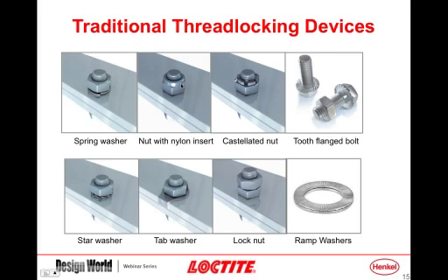The nylon insert takes a different approach. Here they're actually using a material to fill in the empty space on the threads. And it's an interesting approach, but it doesn't fill the load-bearing threads. The nylon insert is typically a non-load-bearing thread. And in many cases, its most effective use is just to prevent the nut from coming completely loose. Lock nut, well, if one nut's good, let's try two. And then with the ramp washer, again, increase the friction.